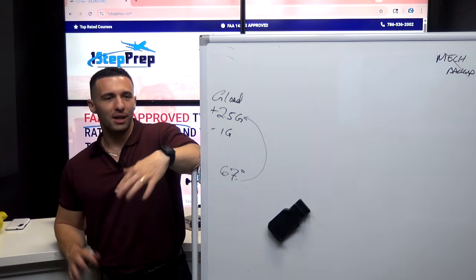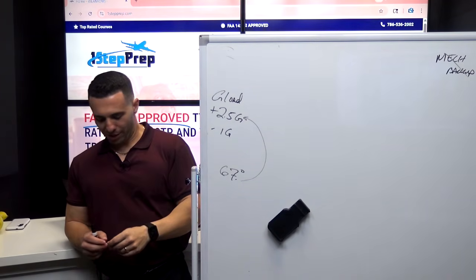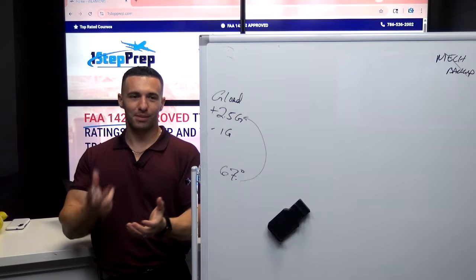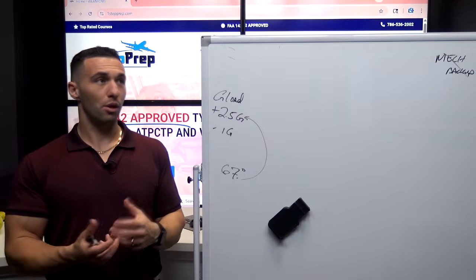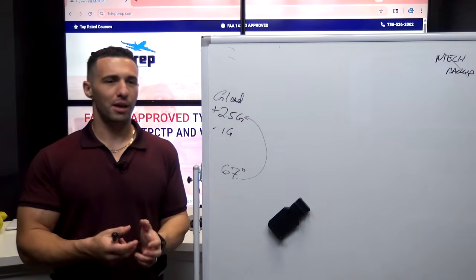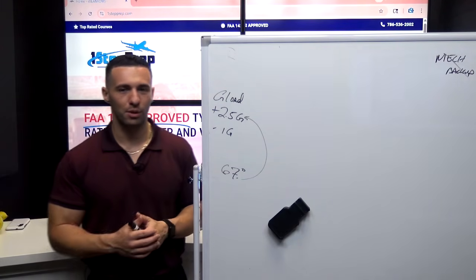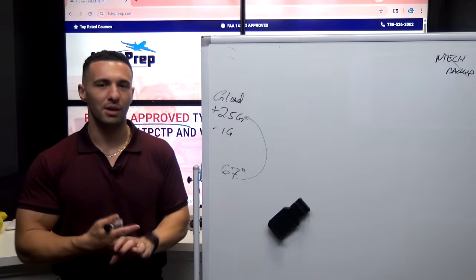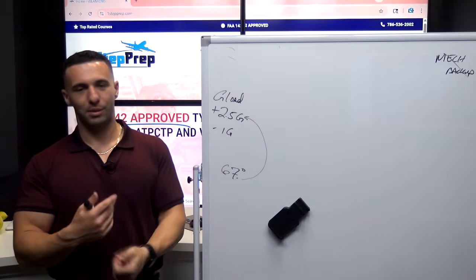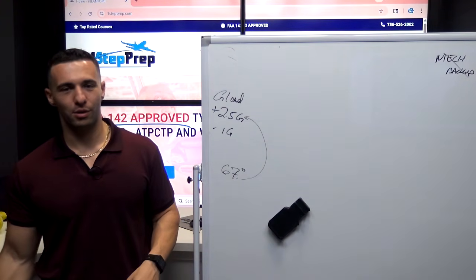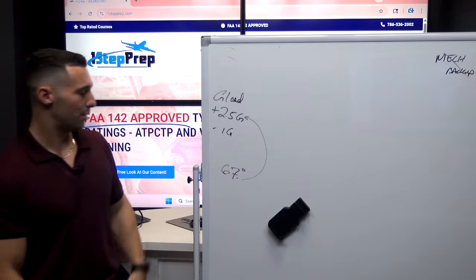And then you go to the FCOM. I've got to tell you, the Airbus, I love this machine. I don't want to fly anything else. But by comparison to some other jets where you just do memory items and QRH, the procedures can be confusing, where it's like, do we have an OEB? No, we don't have an OEB. Okay, good. Is there a memory item? No, there's no memory item. Okay, does it analyze the ECAM? Does it make sense? Because it spits out ECAMs by level of priority and not anything logical other than what priority it thinks it is, level 1, 2, or 3. Then we go through the ECAM, then we get to status and stop ECAM, and we have to go through checklist relight reset, then we continue ECAM action complete. Now I have to go to the QRH. If it's not in the QRH, I have to go to the FCOM. If it's not in the FCOM, there's even a flight crew training manual. It's like, the procedure is quite lengthy.